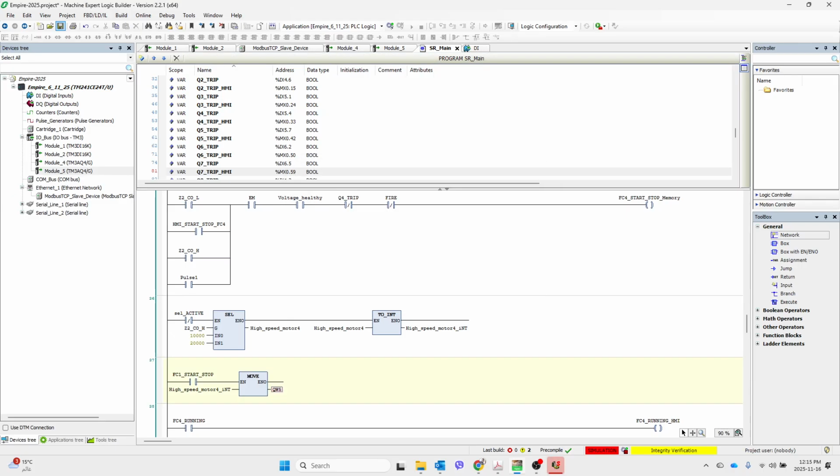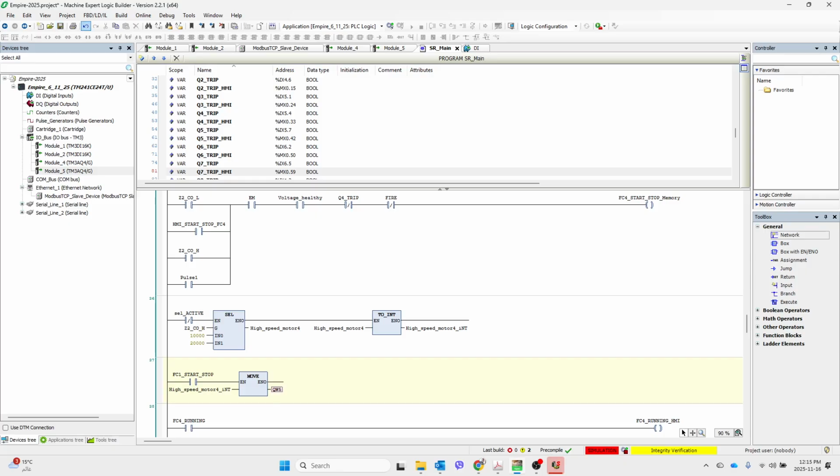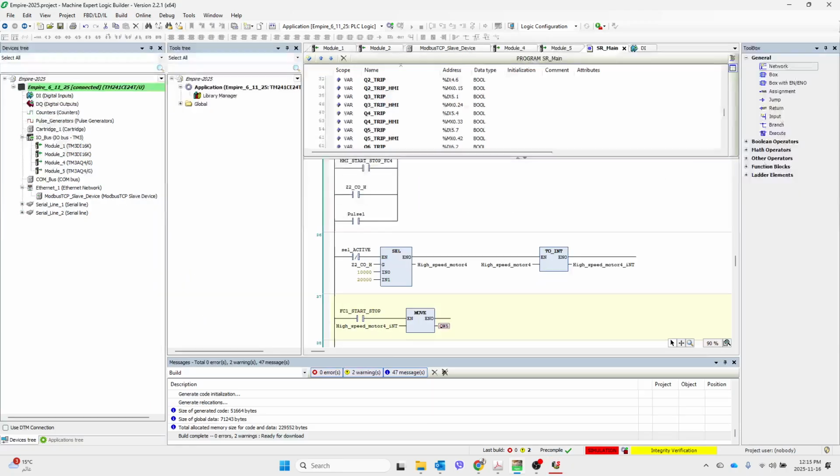Okay, now if you see the second module, I have QW6 corresponds to the current one, input to 1 of output, the second slot of the analog output, the first card is QW6, the address. Now let's assess with this amount. Let's go to the online mode. If you have the device in simulation mode, then you will click online. It looks like you have the device next to you. Make sure that you go online.